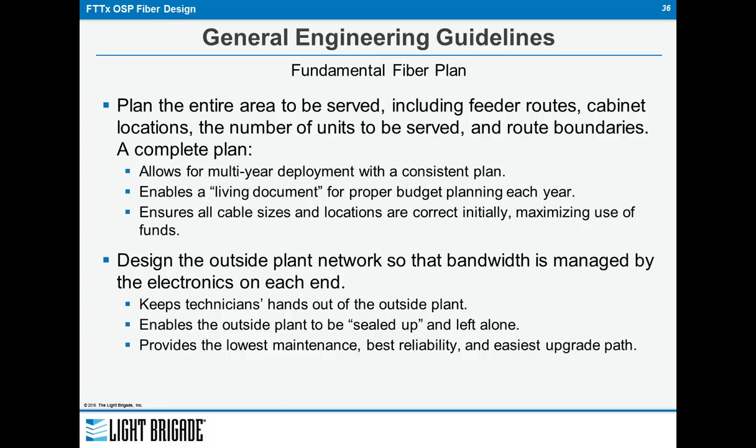Plan the route. Lay out all of your cables, their cabinet locations, who's going to be served and by what, where they fall within the boundary. Have a multi-year plan. Be consistent. Make modifications. Keep good records. And that final statement is, don't design the network with the thought process of going back in and rearranging fiber counts to meet the need.